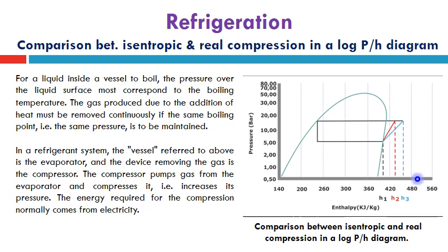This difference increases the work of the compressor, and that will affect the COP badly, decreasing the COP due to the actual compression process that happens inside this cycle, and switches the simple ideal cycle to be a real cycle when implementing the effect of the non-isentropic compression.